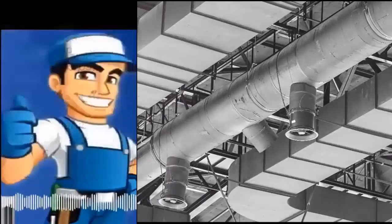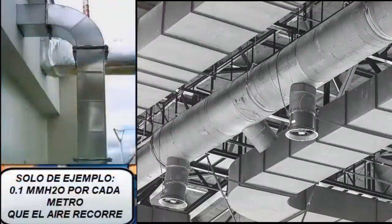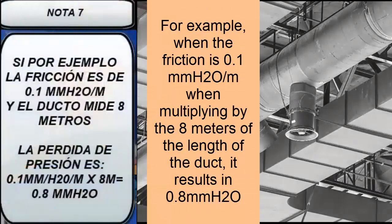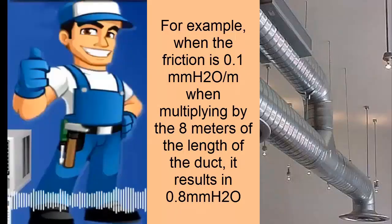Note 6. The air, when passing through the ducts, suffers a loss of pressure due to friction. These losses in some cases are close to 0.1 millimeters of water column for each meter. Note 7. If, for example, for an 8-meter duct, the pressure loss due to friction is calculated by multiplying the 0.1 millimeters of friction by the 8-meter duct. Thus we have a loss of 0.8 millimeters of water column. We stay in note 8.